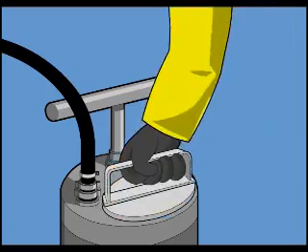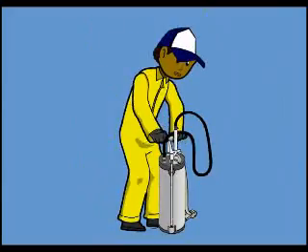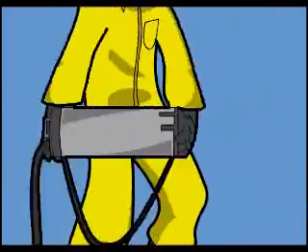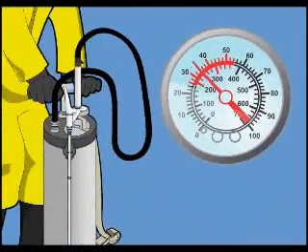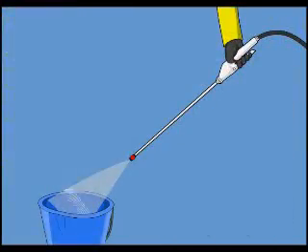When the sprayer has been depressurized, the tank can be cleaned by filling it half full with water. Replace the lid. Pressurize the tank slightly and then shake it to ensure all the inside surfaces are washed. Pump again so that the pressure is up to 2.5 bar, and spray the water through the nozzle so that the hose, trigger valve, lance, CFV, and nozzle are clean.